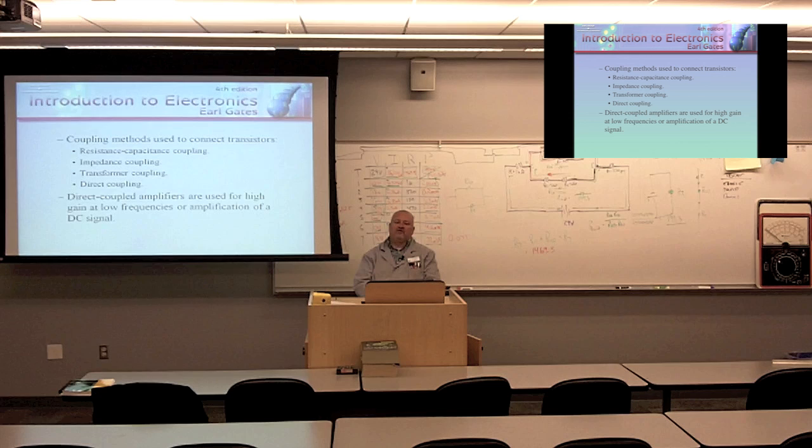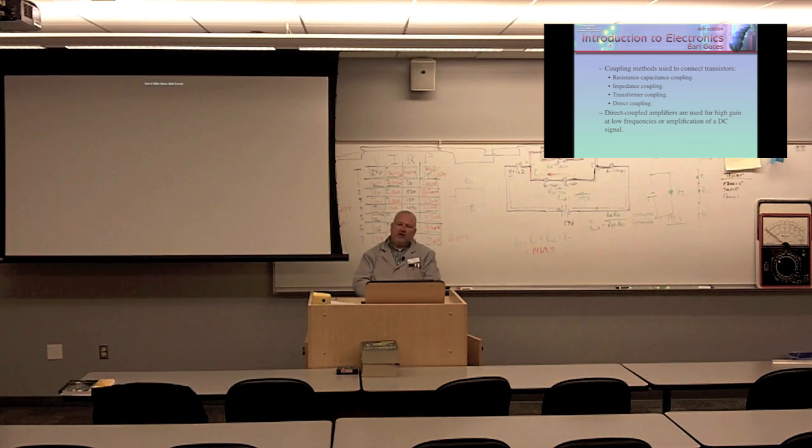Coupling methods: RC, resistive capacitive; impedance, which utilizes an inductor in place of the resistor; transformer coupling; and direct coupling. Direct coupled amplifiers are used for high gain at low frequencies or amplification of a DC signal. Anybody have any questions?